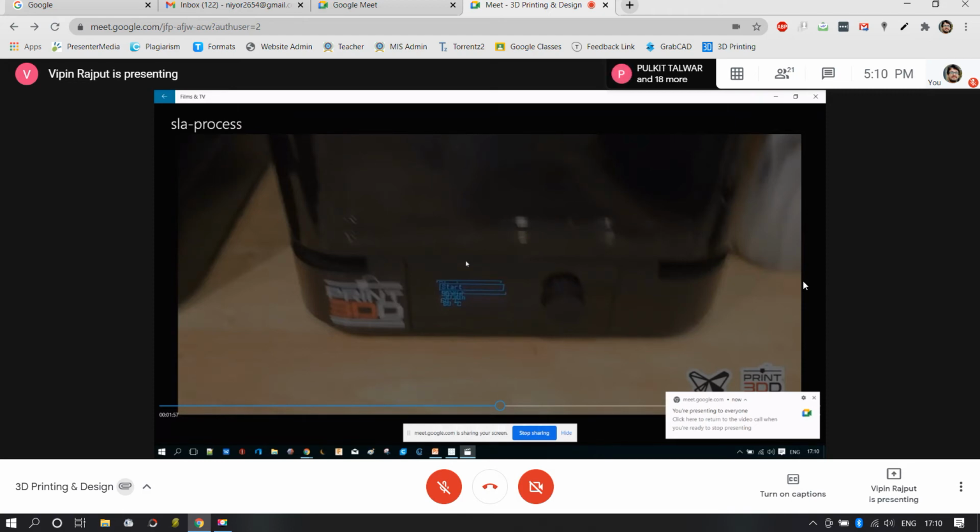Let's say if you have dipped your hand into a polymer bin and thus have liquid polymer on your hands, you can simply wash your hands with isopropyl alcohol and everything will be dissolved into it. An alternative to this is a soap solution, but we cannot use that solution to clean the parts. That's why we use isopropyl alcohol with 85% plus concentration to treat the parts.